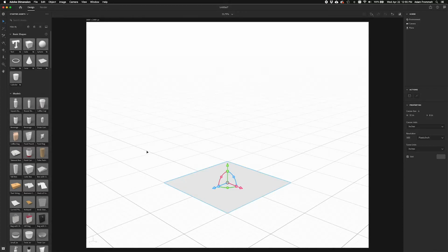What I'm going to do to set up a backdrop for the prototype that I'm going to place in here, I'm just going to use a couple planes. I'm going to get them sized and positioned here. And then later when we get to step 2 in the modeling process, adding materials, remember 3D modeling is a 4-step process. Number 1, we build. So we get our objects, models, into the actual scene or environment. Number 2, we texture. And for us here in Dimension, that's adding materials to our models or 3D objects.